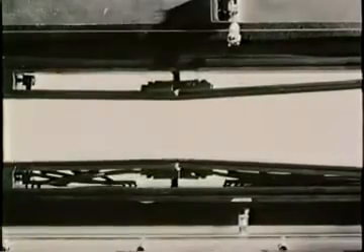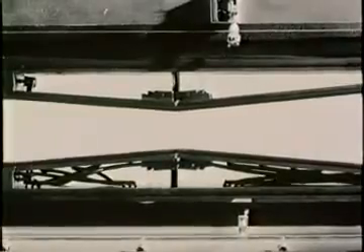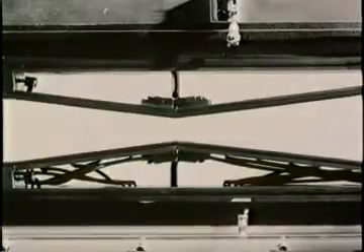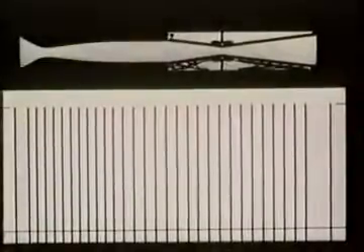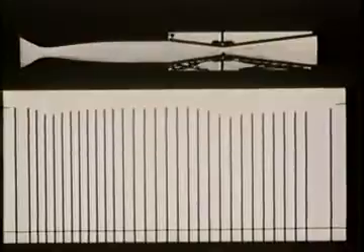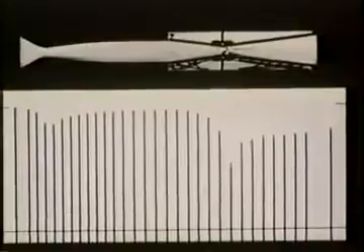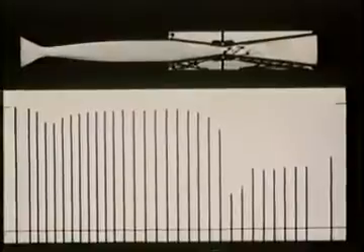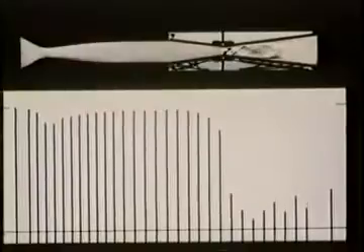We now have two means of control over the flow in our channel: the geometry of the second throat and our original control valve. Let's begin by making the second throat smaller than the first one. As we open the valve, the channel chokes in the usual way. But at the second throat, the upstream flow is subsonic and independent of downstream conditions. All that we can do with our control valve is to move the terminal shock wave without affecting the flow upstream.